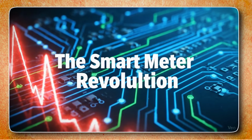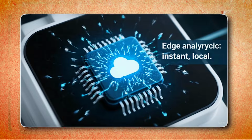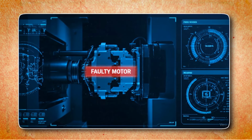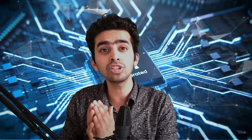But with source identification, AI-based models running inside an energy meter, the smart energy meter doesn't just raise an alert on harmonic distortion. It identifies the source. Harmonics are originating from the 3D printer in the prototyping area. This response is instant, right from the edge device, without any delay or need for cloud analysis. And that is the value of real-time source identification. The maintenance team knows exactly where the problem is coming from. Troubleshooting is fast, accurate and focused, and the system turns from passive monitoring to active diagnostics.